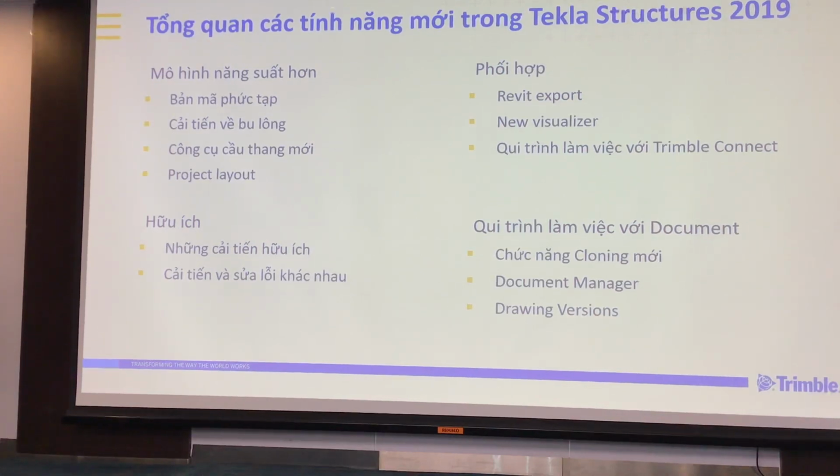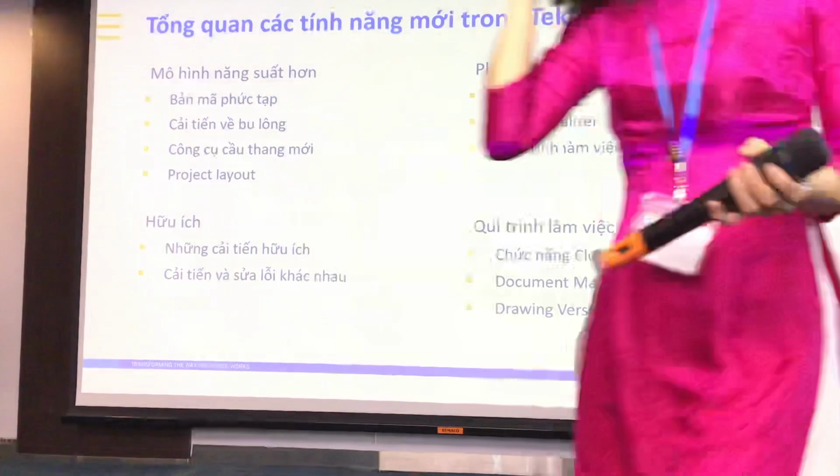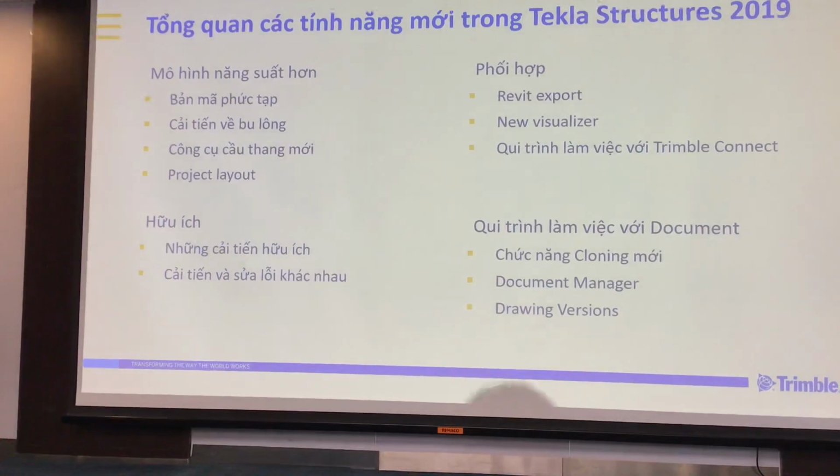And we can put it into CNC? Yes, it unfolds. That's a great question. Yes, it also unfolds to CNC. When you create the CNC file, it's unfolded. So any of these bent spiral pieces, or the ones I put in, when you create the CNC file, they're automatically unfolded and ready for CNC. Again, I'm going to be at the back. If you want to see it live, I'll show you. To show you I'm not lying, I assure you, I always tell the truth, so I'll show you.